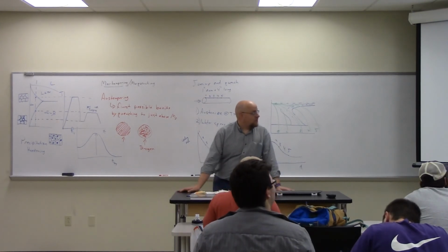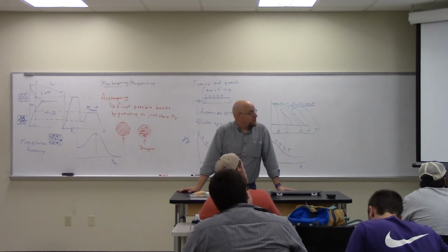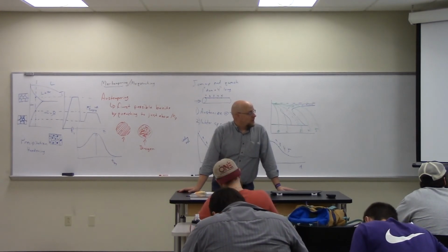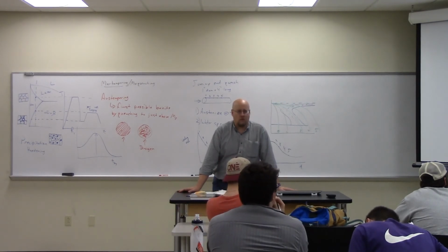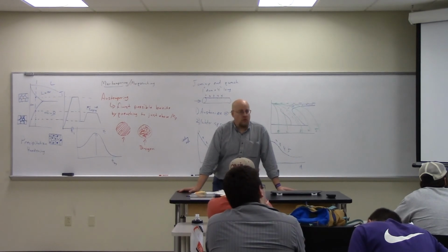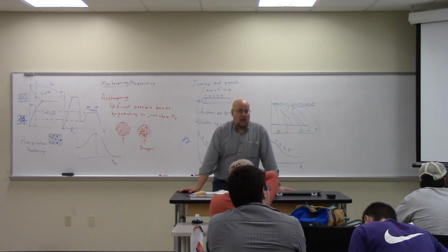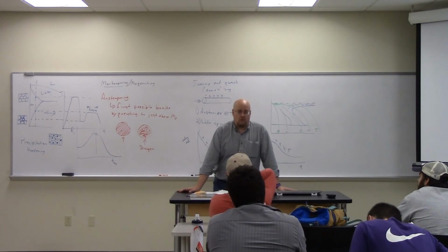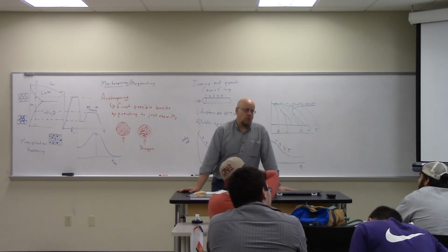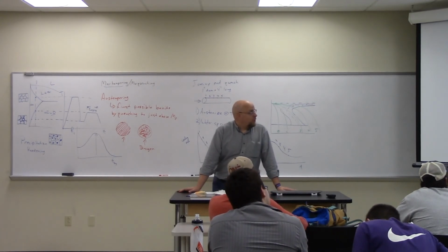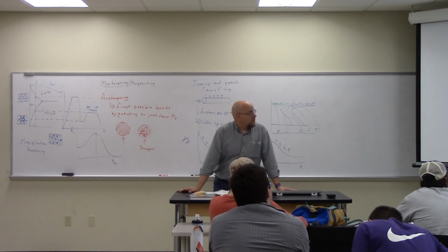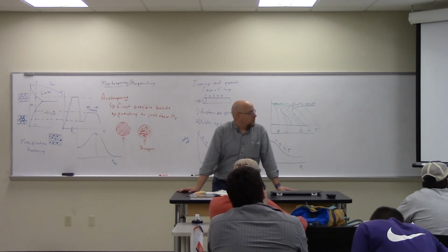Okay, we have a eutectoid steel that's cooled at a steady rate from 727 to 200 degrees C in exactly 1 day. So we take 1 day to gradually cool from 727 down to 200. The way you would do this normally is you would leave it in a furnace and gradually dial down the temperature of the furnace from 727 to 200, because you can't really have a controlled cool otherwise for this long period. So superimpose this cooling curve on the TTT diagram of figure 10.11, which is shown below there.